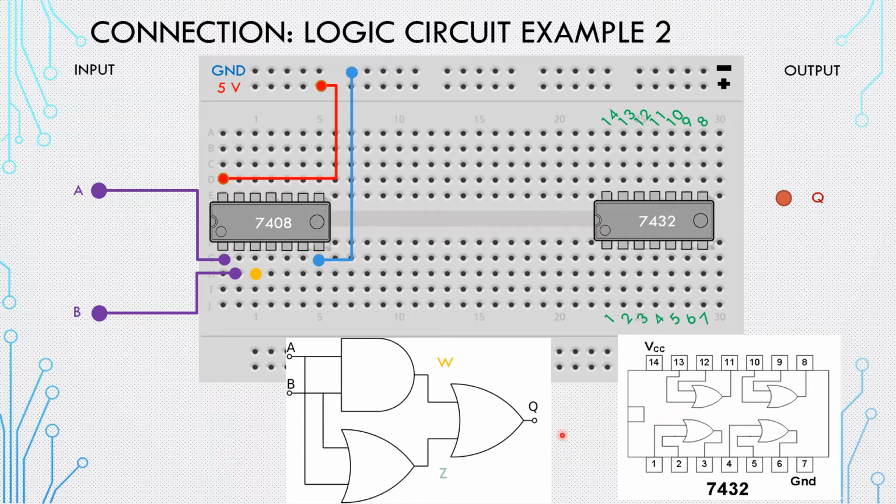I'm gonna connect. At the beginning you need to power up the IC. How to power up the IC? You need to know the numbers order for the IC by looking for the notch, starting from here: 1, 2, ... 7 and it's 14. So 14 gonna connect it to 5 volt, and for 7 we're gonna connect it to the ground. So now I power up the IC.